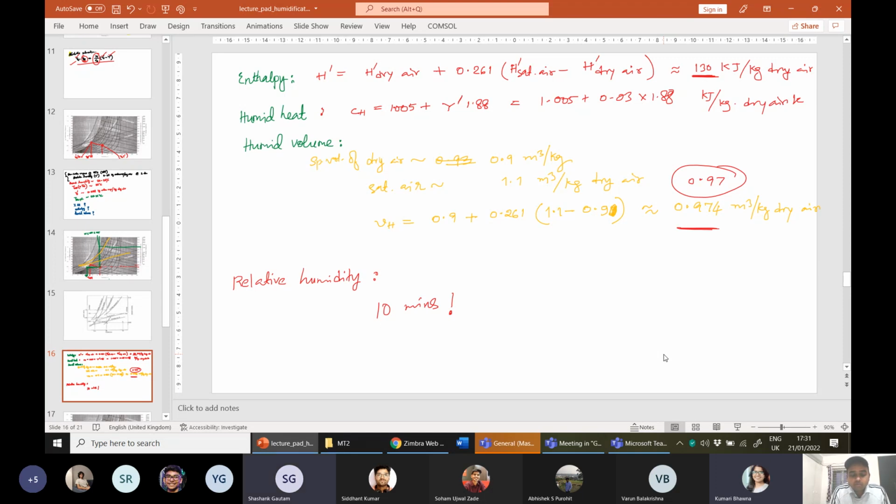Sir, can we do it this way? We draw a vertical line from the dry bulb temperature axis at 55, and then we draw a line of the wet bulb temperature. Say, continue.